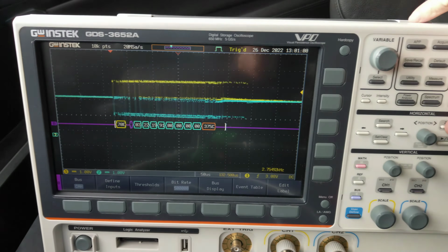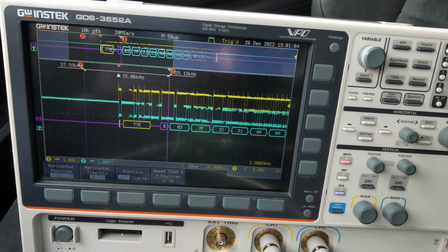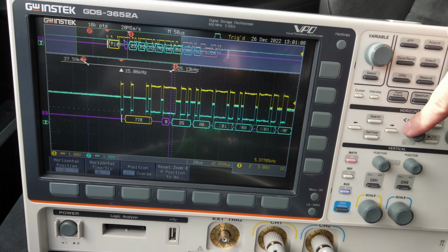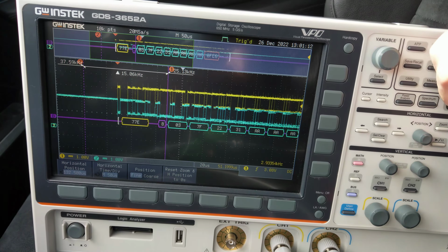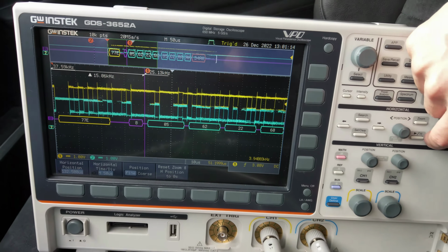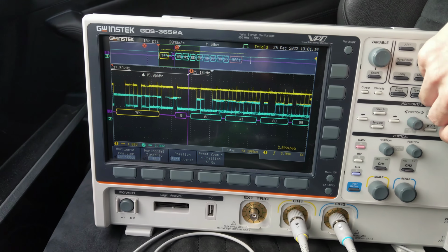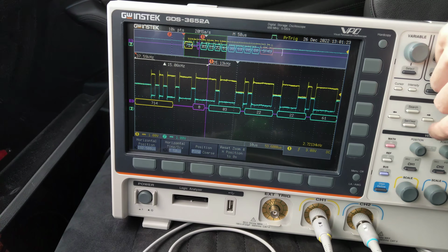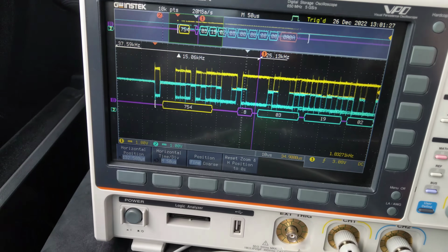Regarding the waveform, any interference here? Check it. Zoom in. Check detail. The waveform appears better than what I thought. I assumed there would be some noise, but there isn't. There are only some burrs that are noticeably appearing at both the top and the bottom edges of the waveform. Essentially, this waveform, to me, is fairly clean. I believe it's quite clean. Regarding the burrs, I believe the burrs at this level are acceptable.